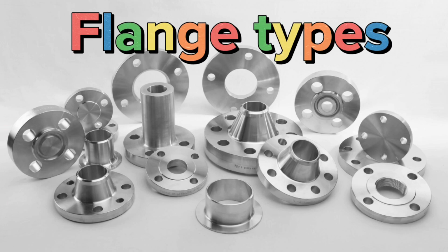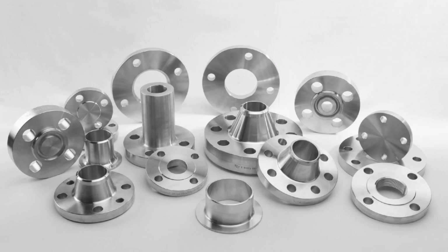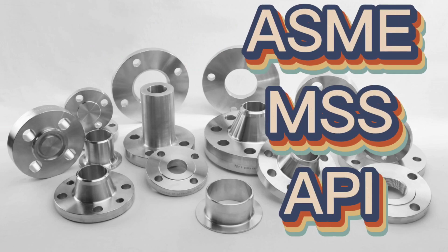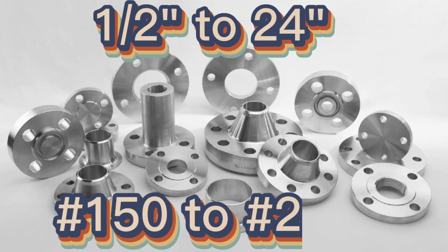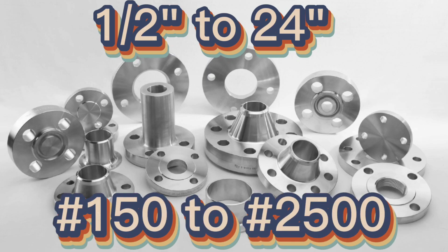Flanges are the construction element used to connect pipes, valves, and pumps to form a piping system. In other words, it is the connection used to join the pipes. Flanges are standardized according to publications from organizations like ASME, MSS, API and others. Flange dimensions are for pipes ranging from 1/2 to 24 inches, in classes ranging from 150 to 2500.